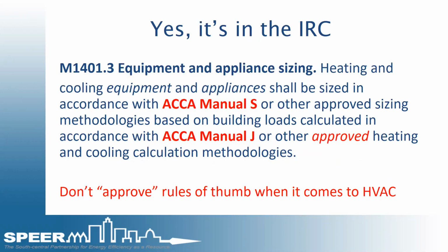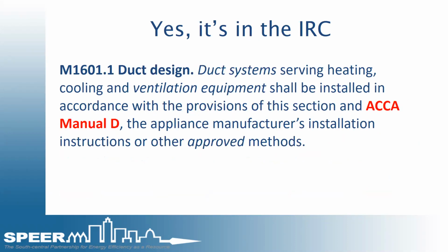So just so you know, yes, this is in the IRC. So as a code official, you are more than within your jurisdiction, and code, you know, it's straight out of the IRC. It says, hey, use ACCA Manual S for selecting the equipment based on the Manual J loads, right? Rules of thumb, not so good. And yes, Manual D is in there as well under duct design.